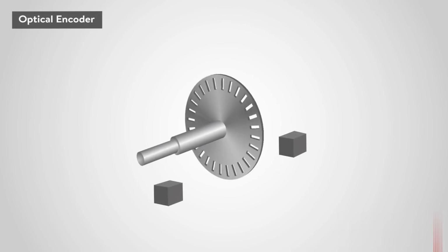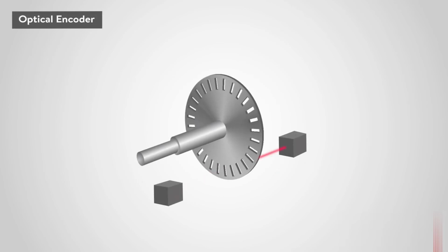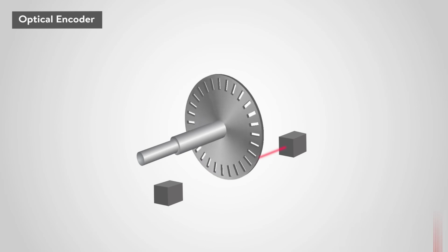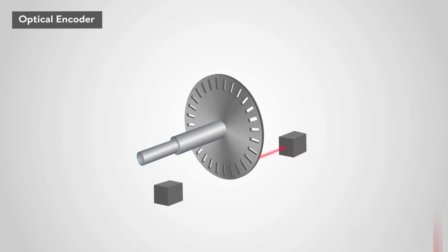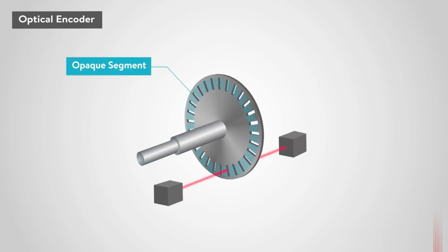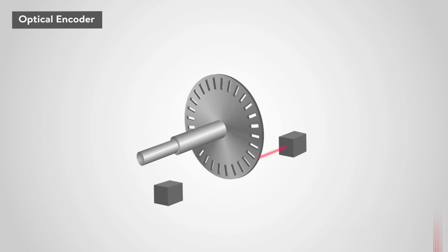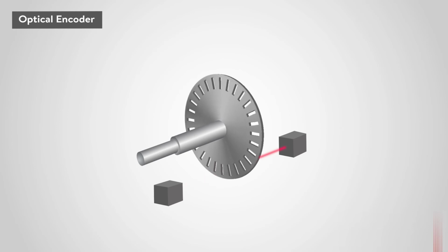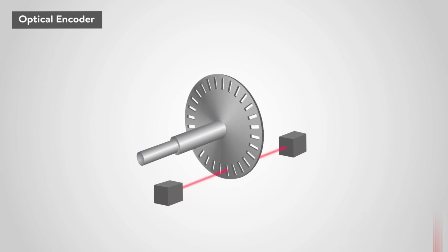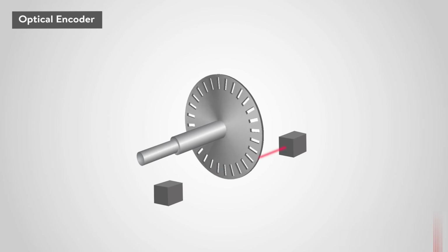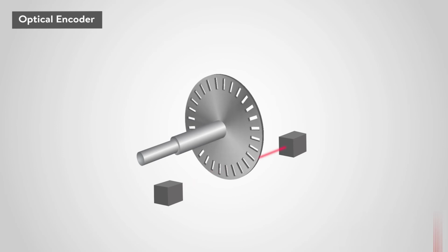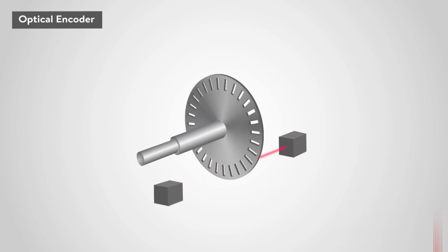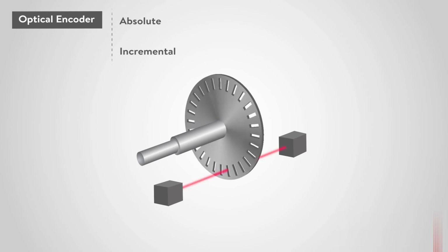Optical encoders interpret data in pulses of light, which can then be used to determine such things as position, direction, and velocity. The shaft rotates a disc with opaque segments that represent a particular pattern. These encoders can determine movement of an object for rotary or shaft applications, while determining exact position in linear functions. Optical encoders are used in various applications, such as printers, CNC milling machines, and robotics. Again, these encoders may be absolute or incremental.